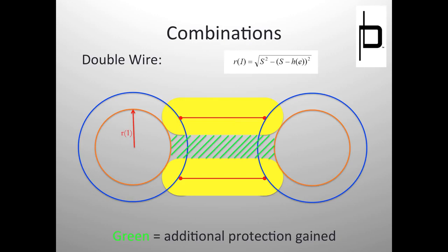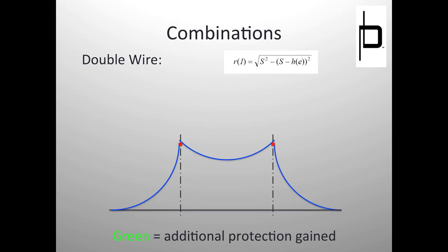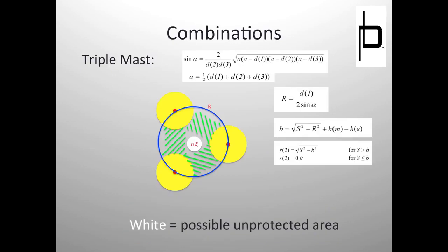You're going to hold that sphere up the whole way. And now, because the wires are exactly the radius of the sphere, or just less than the radius of the sphere, I should note that the farther you spread these two apart, the lower the sphere begins to droop, and eventually it cuts into your equipment height. Your equipment may be this tall or whatever it is, but as long as the two wires are close enough together to not allow the sphere to cut into your equipment height, everything between those two wires is protected. So that's pretty cool.